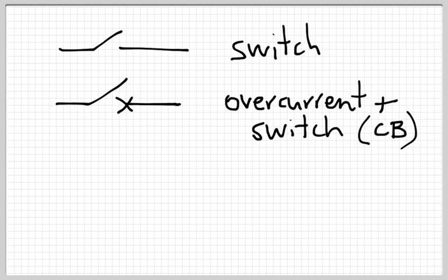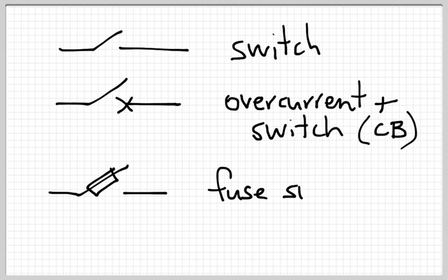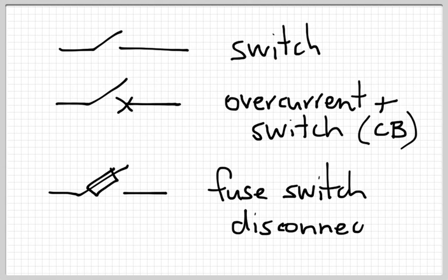And you also get what we call fuse switches, which is a fuse and a switch in one. So we'll call that a fuse switch. More technically, it's called a fuse switch disconnector. Love those really overly complicated terms, but that's what it is. And that's what you'll often find as the main isolator in a battery system.